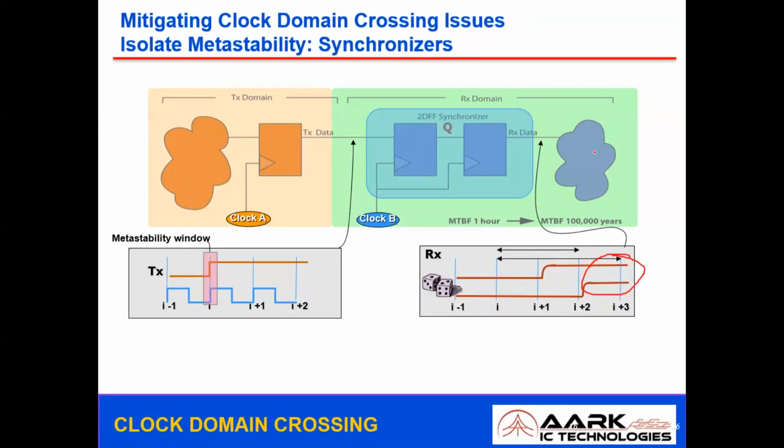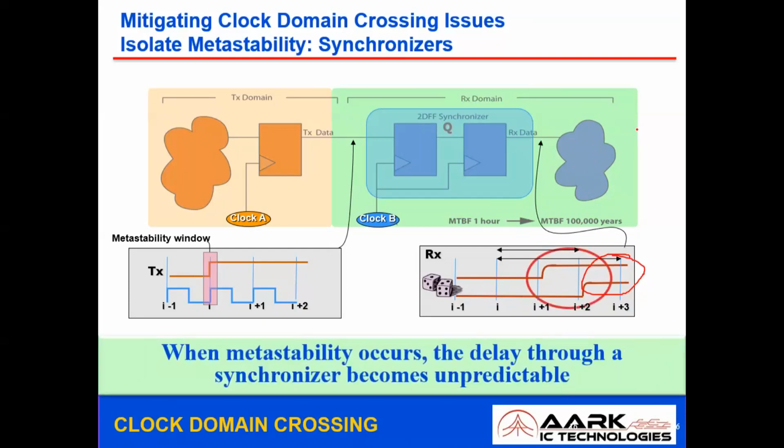So by the time it reaches this register or this design block, your data is stable. So this is how we can avoid the metastable states. By simply adding synchronizers, we are not completely rectifying these issues. What we are trying to do is reduce the occurrence of this. That means we are prolonging the occurrence of this error. That is the mean time between failures.